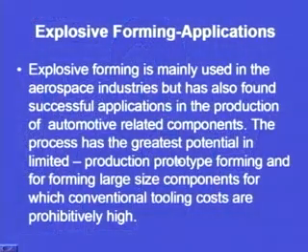Depending upon the final specifications or requirements of our product, we decide on the process that we are going to choose. Explosive forming has been readily used in the aerospace industry as well as for making certain automotive components. The process has the greatest potential in limited production prototype forming and for forming large size components for which conventional tooling costs are prohibitively high.